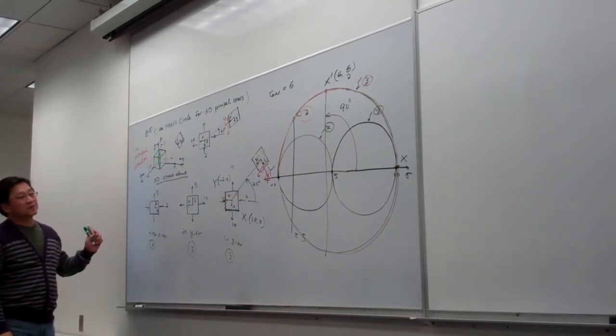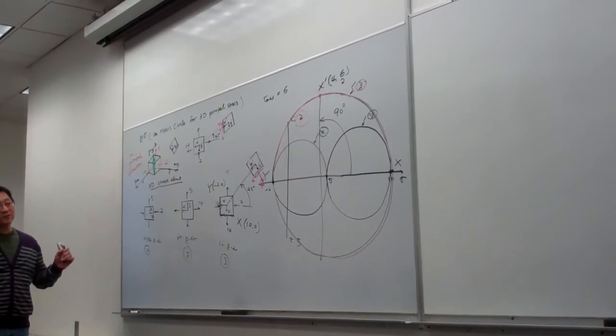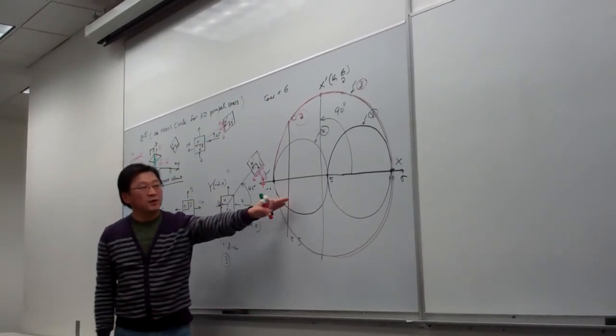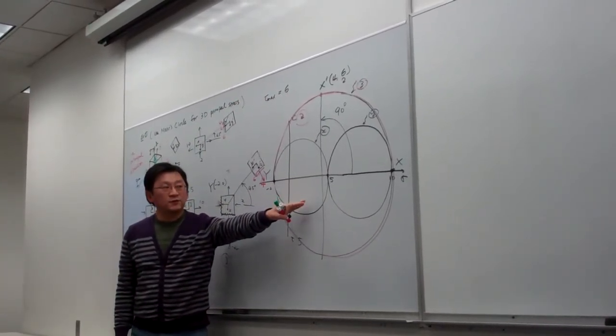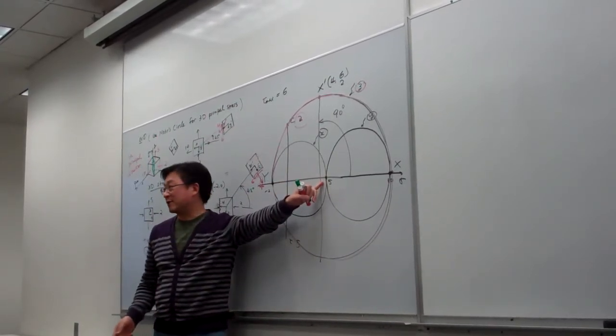So that is the application of the principal stresses for the three-dimensional case. And again, for a three-dimensional stress element, we always expect three circles, and the three circles must be tangent to one another.